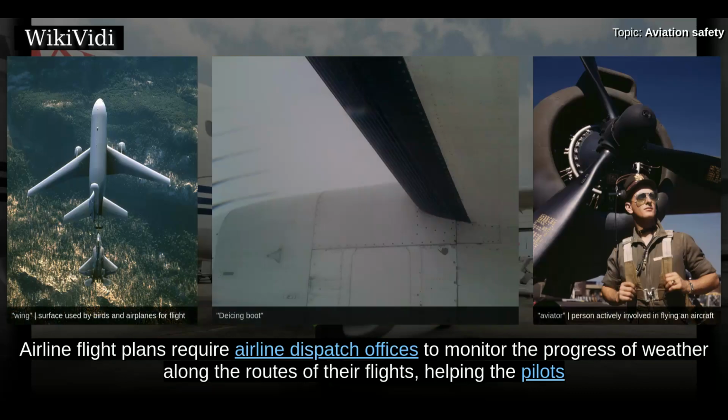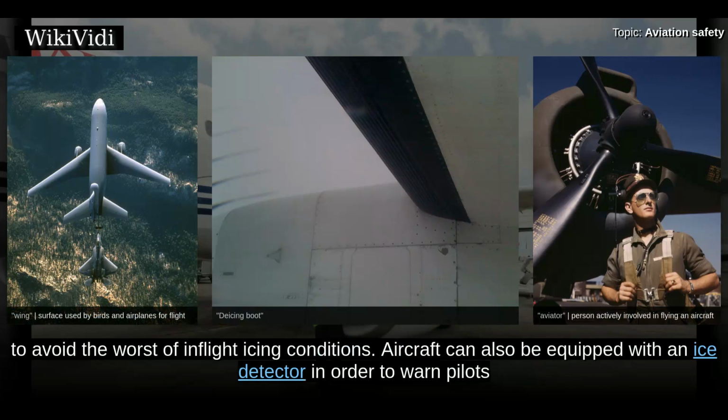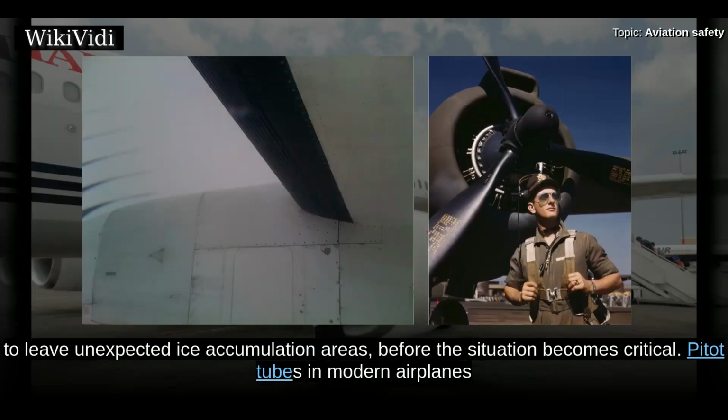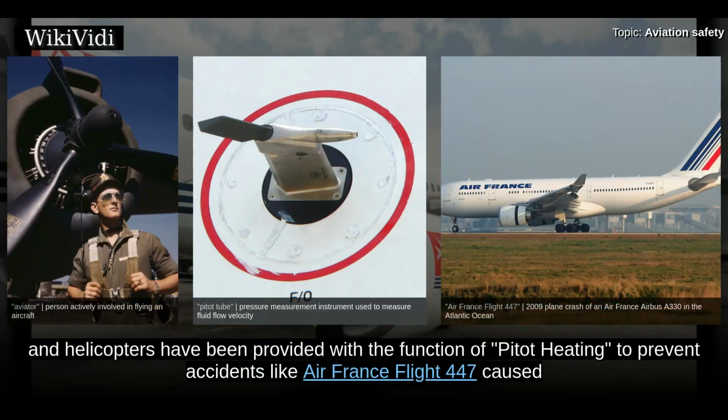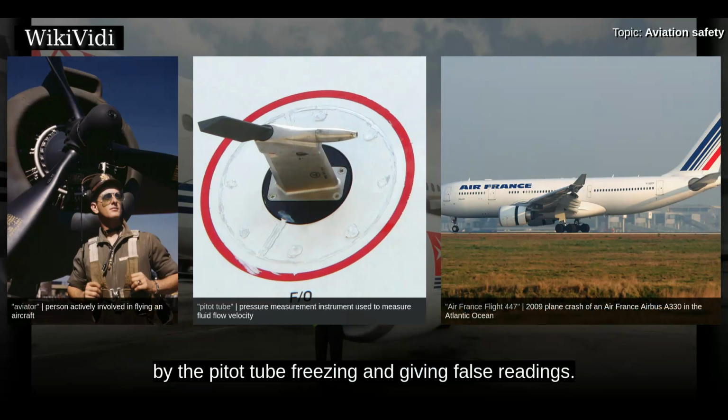Airline flight plans require airline dispatch offices to monitor the progress of weather along the routes of their flights, helping the pilots to avoid the worst of in-flight icing conditions. Aircraft can also be equipped with an ice detector in order to warn pilots to leave unexpected ice accumulation areas before the situation becomes critical. Pitot tubes in modern airplanes and helicopters have been provided with pitot heating, to prevent accidents like Air France Flight 447, caused by the pitot tube freezing and giving false readings.